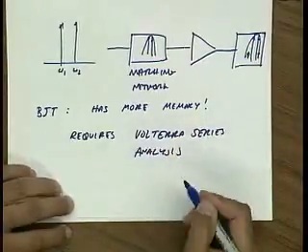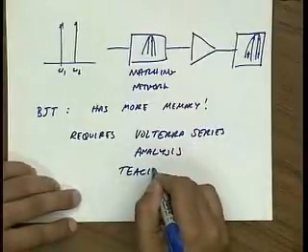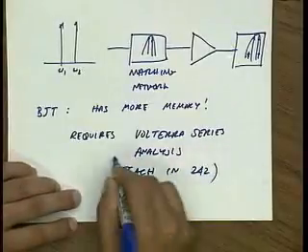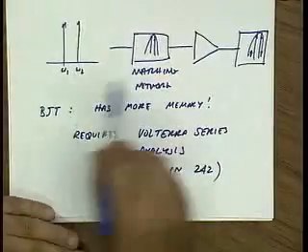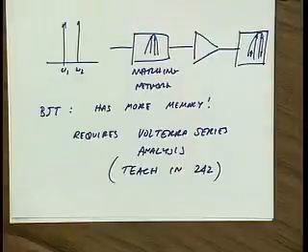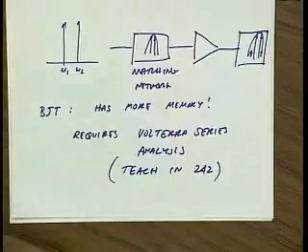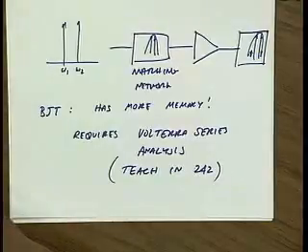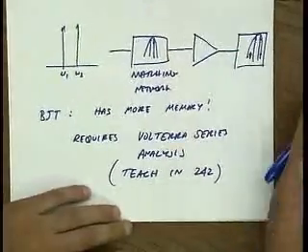This is something that we teach in 242. But it lets you take into account the memory effects in a bipolar. What are some of the memory effects in a bipolar? Exactly. It's the tau f. It's the diffusion capacitance. You have the nonlinear junction caps just like you do in a MOS, but then you have this diffusion capacitance, which in combination with the junction capacitances makes the device have memory. Okay? Any questions?